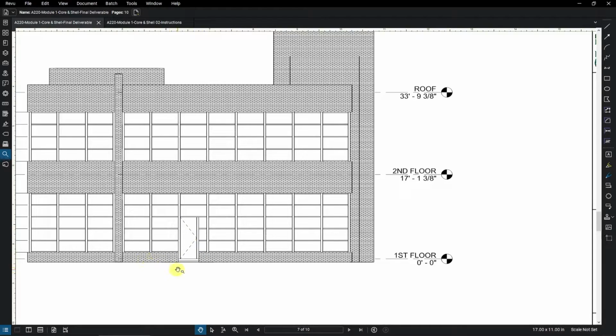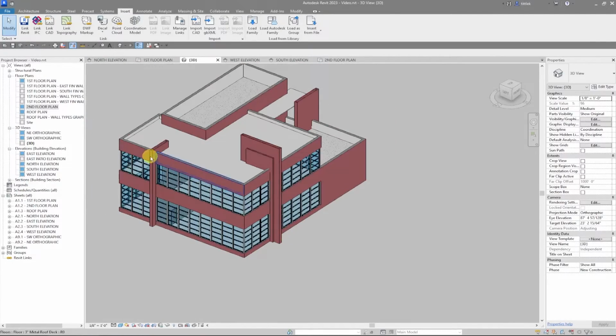So again, same steps. We have to add a mullion, and you can do all this. Again, you can place it and worry about the dimensions later once we go into plan, which we're going to do here in a second. And then add a mullion, remove certain line segments, add the door, and you should be able to do that since I showed you that earlier. The only thing left to do now is to dimension all of this stuff.